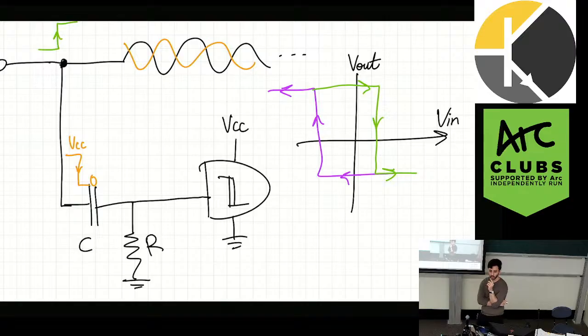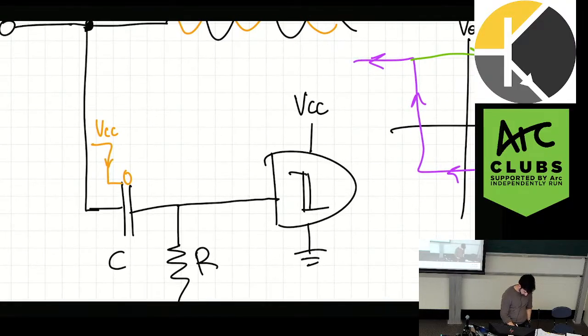So think about what happens on the right side of the capacitor. Any ideas? It would remain the same. What would remain the same? So this voltage was sitting at 0 volts on the right-hand side from the last scenario we were just in, because it's already discharged. So it starts at 0, and then drops down to what voltage? Negative VCC, right? It matches what it sees. So it goes from 0 to negative VCC.